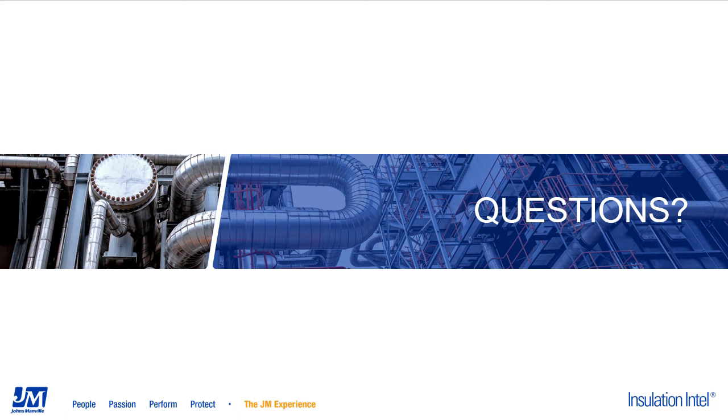I've heard 250, 300, 350 at different times from different people. So you have much less of a concern with stainless steel operating in cyclical nature, because once it gets below 140, the chemical reaction of stress corrosion cracking is slowed to insignificance.